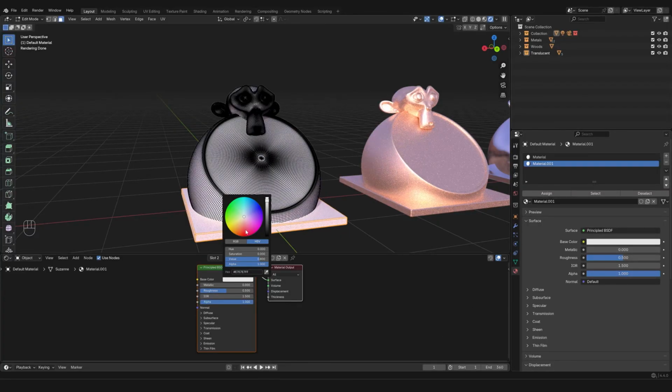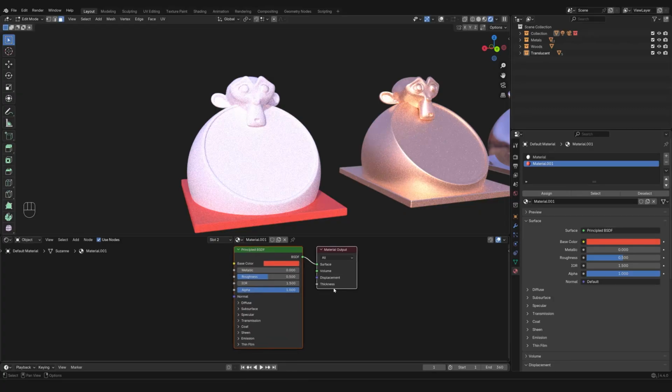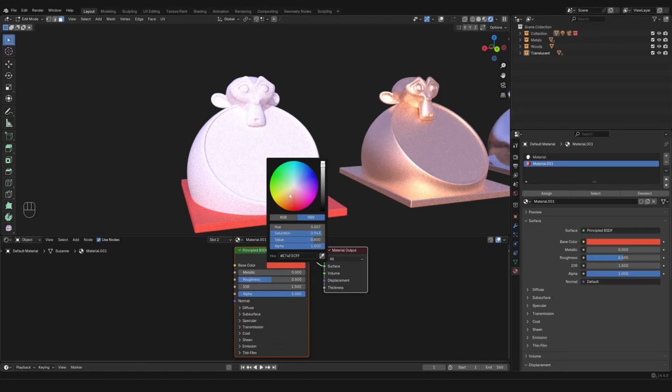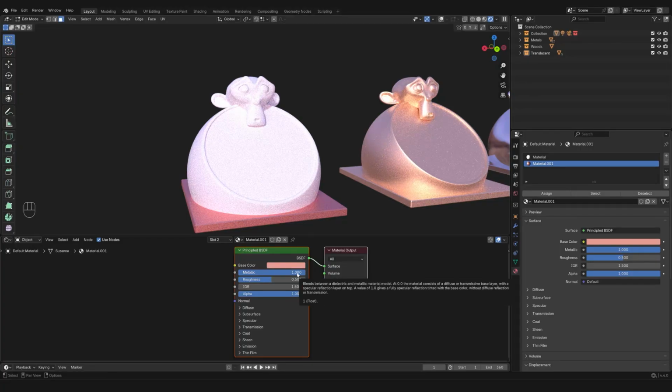And if this was of a different color, it would become apparent that within the same object, we now have two materials, and this one is the second one. So this part of the mesh has been assigned this material. And while we're at it, we can review the basic properties of materials. What we have looked at so far is the basic color, which can be changed easily from this menu. The metallic property, which, reminder, should always be either 0 or 1.